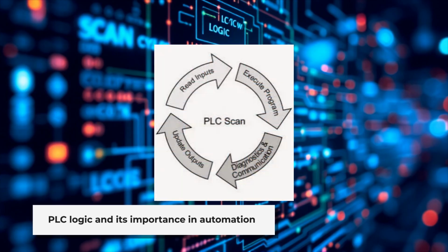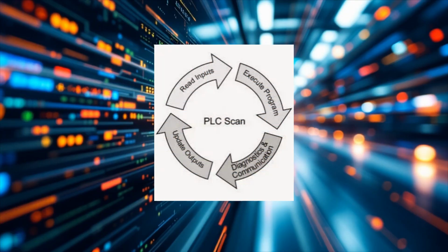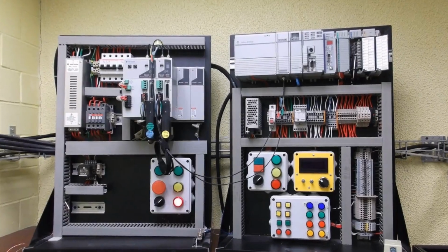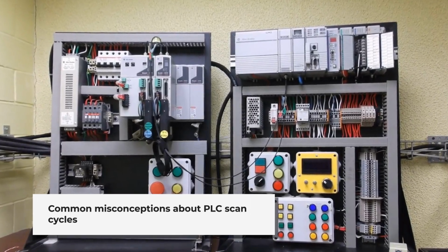At the heart of PLC programming is the execution of the PLC logic. The running of the PLC controller is also known as the scan. Scan and scan time are essential to understand in automation. Scan cycles run cyclically. This means that they repeat continuously at a very high speed, which allows for real-time control of your automation project.